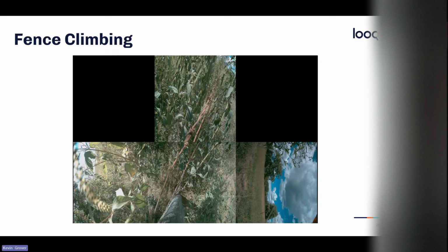One of the things is climbing fences, the other bane of our existence too. You can climb fences, but you have to basically keep the device pointed upright. We know there are a lot of logistical challenges of walking in some of these rural areas, or in and around other equipment and features. What you want to avoid when you're walking is dumping the device, and us not being able to keep tracking and image matching and having proper GNSS.